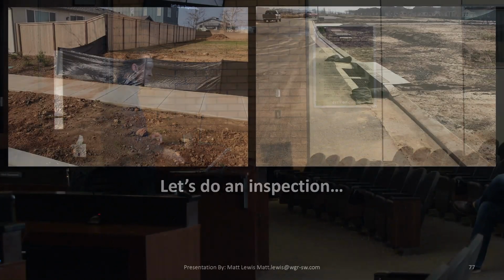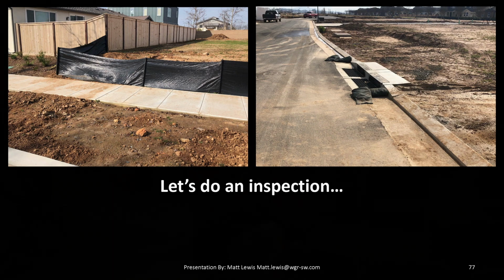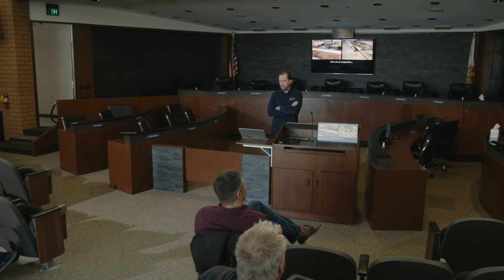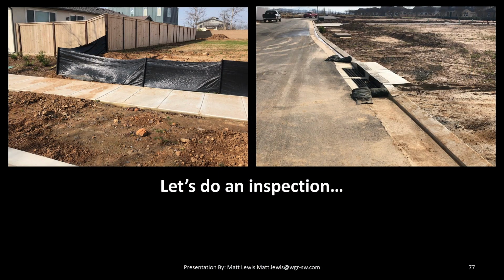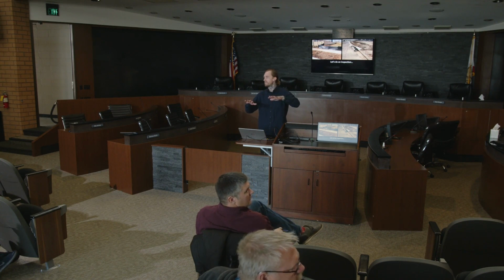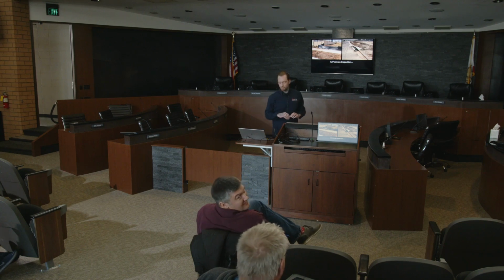Okay. Kind of more of the same. This is all the same site if you had to guess. Yeah, the fence is maybe a little high, but that's only because it's not keyed in. And so you can see to the left, there's sediment running across the sidewalk there. If we had this a little blown up, you would be able to see that they didn't key it in, and wind, that's just wind erosion, is blowing those silt fences and kicking that sediment across the sidewalk.